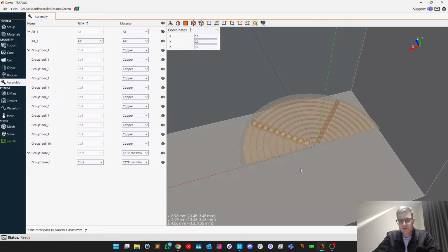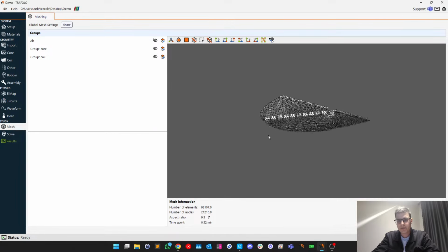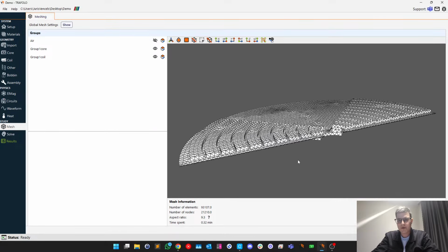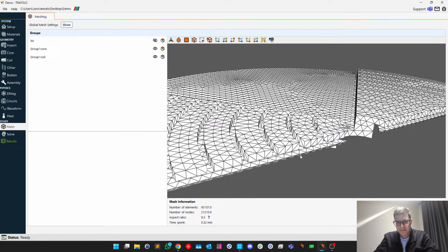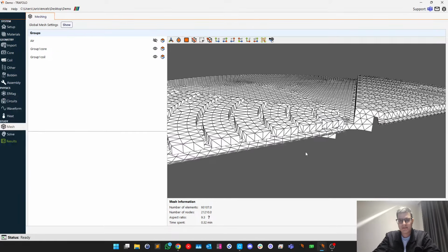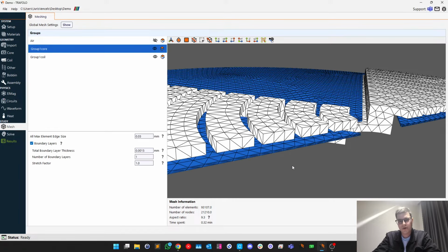You solved as a symmetric problem. We advise you not to jump into full geometries, but rather first always solve and try to reduce your problem to a symmetric. You will save a ton of time and effort, and this time and effort could be spent in things that really matter. And the things that really matter for such planar magnetics is, guess what? Mesh.